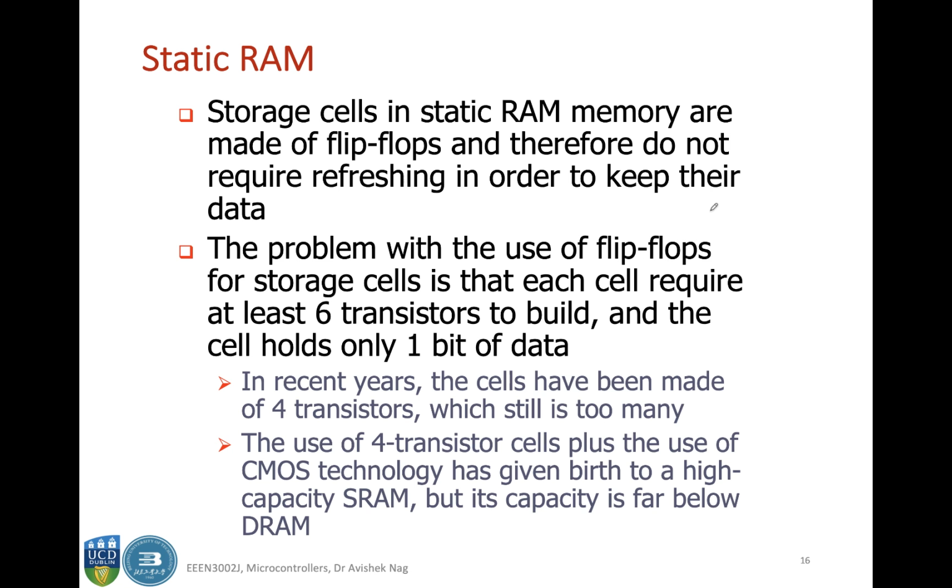The RAM is made of several flip-flops, and if you are storing 1 or 0 in those individual flip-flops, that will stay unless the power is switched off. But you will see that in some types of RAMs you use capacitors instead of flip-flops. In those cases you have to refresh the charge of those capacitors in order to keep the data.